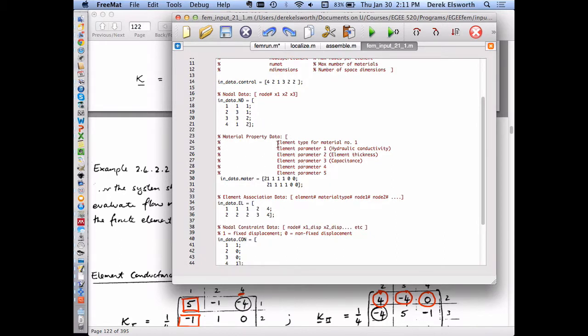The elements. Well, element type is 2, 1 is this, I said. 2 means 2-dimensional. Triangular elements in this particular case. 1 means for these flow problems. That's just my little code to do that. And you then prescribe in this element subroutine what it is that the parameters are that control it. If it's a heat flow problem, it would be Fourier's thermal conductivity. If it's a diffusion problem, it would be Fick's law. But here it's just a parameter, a series of parameters. Parameter 1 is hydraulic conductivity. Element thickness we need, I guess these 2 things that I mentioned here.